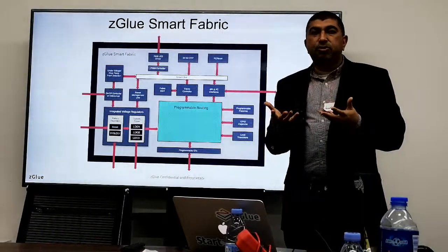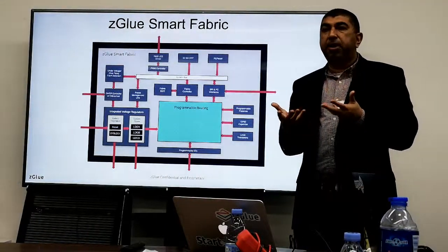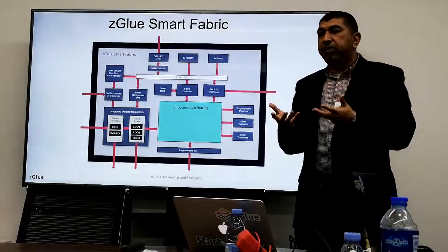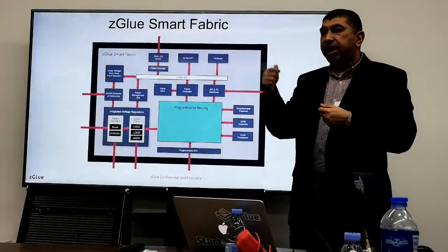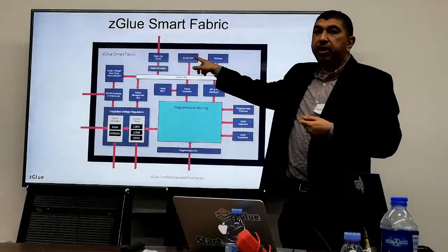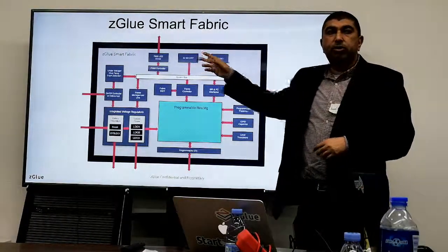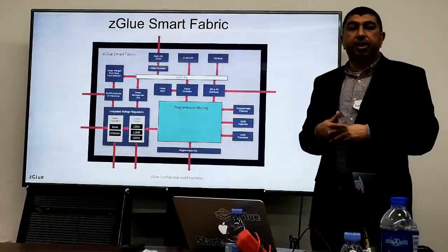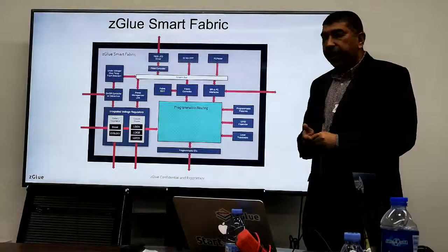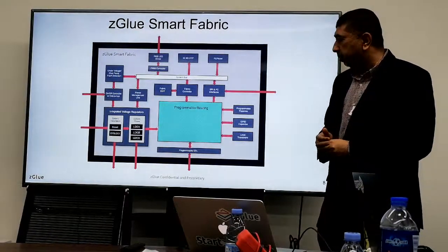And then it hands over the control to the main microprocessor or main microcontroller. And then from there on, the main microcontroller firmware takes over, and that can override what's written in here or part of it. That's also something that's the foundation of over-the-air update. And that's also a technology that we have developed and validated.